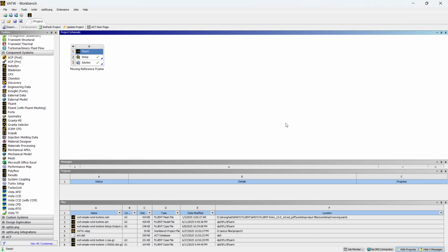Now, let's move on to a different and more dynamic simulation approach, using sliding meshes. There are situations where the MRF method we used earlier might be too much of an oversimplification. Why? Because in MRF, we only simulate one static position of the rotating hub relative to the incoming wind. But in reality, as each blade rotates, it interacts with vortices and flow disturbances left behind by other blades that have just passed. MRF can't fully capture these time-dependent effects.